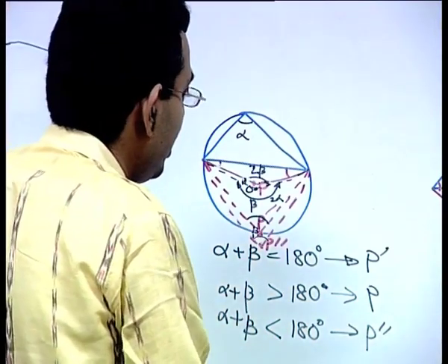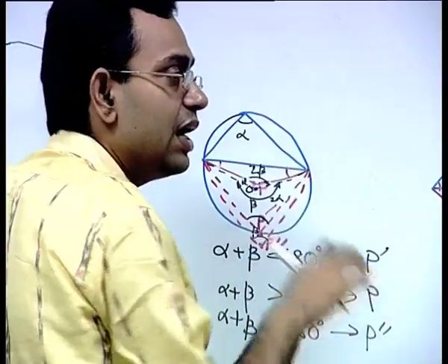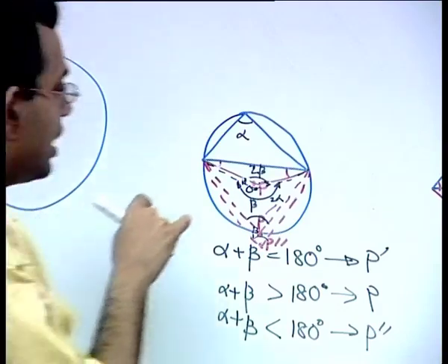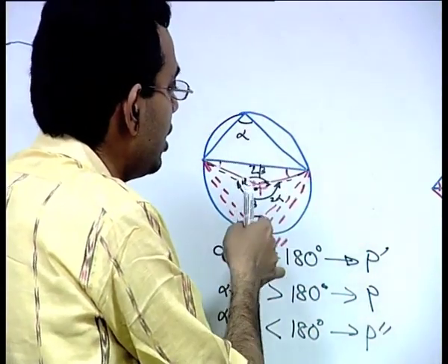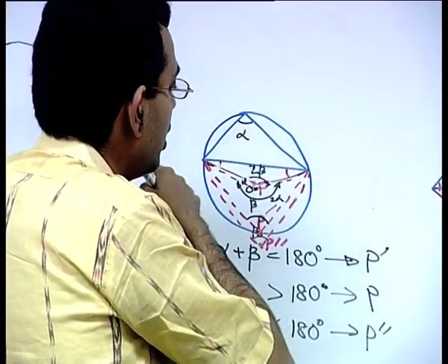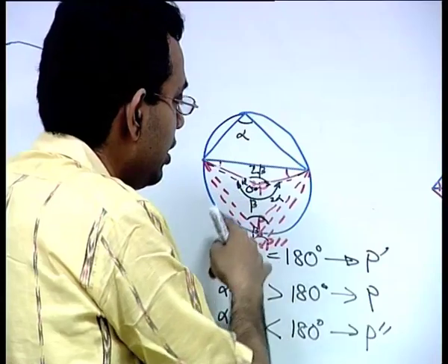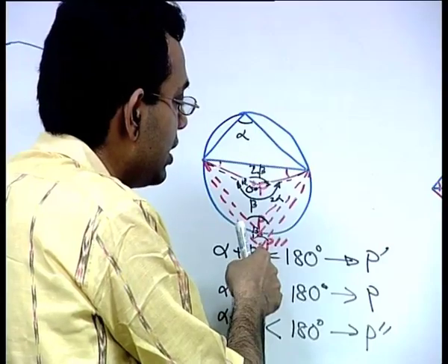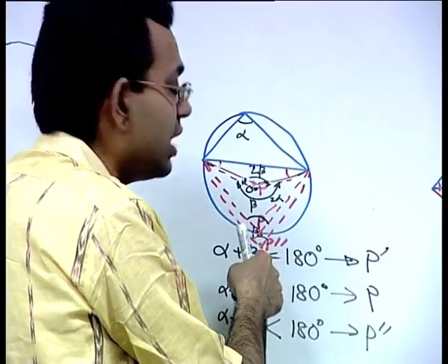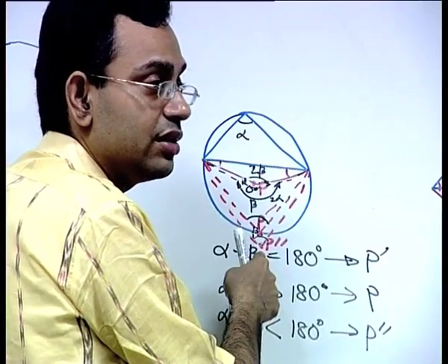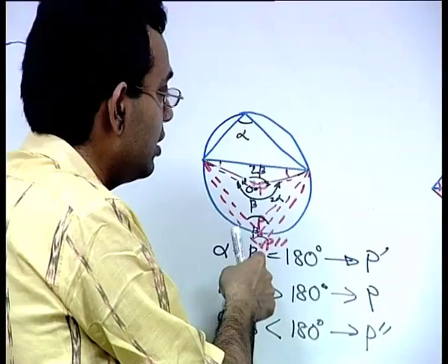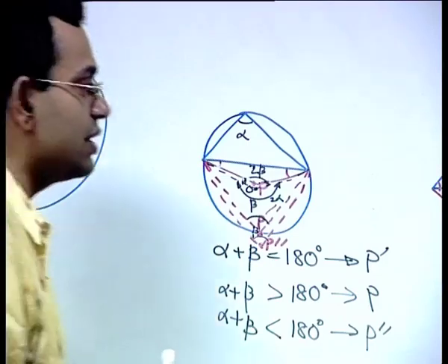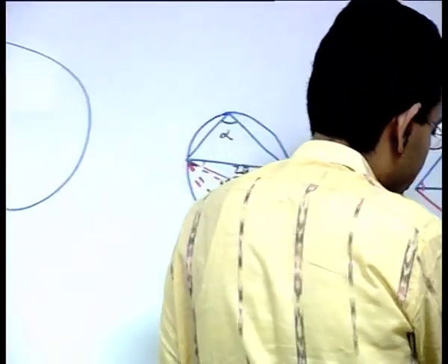So, what we can see is that if you do not want the interior angle to be small, you can create a smallness or largeness criterion by considering that if you have a triangle, you draw a circumcircle, you insert a point, the point P should be inserted in a way that it is falling outside the circumcircle of the original triangle. Then the corresponding new triangle generated is a good triangle. This is called as a circumcircle test.